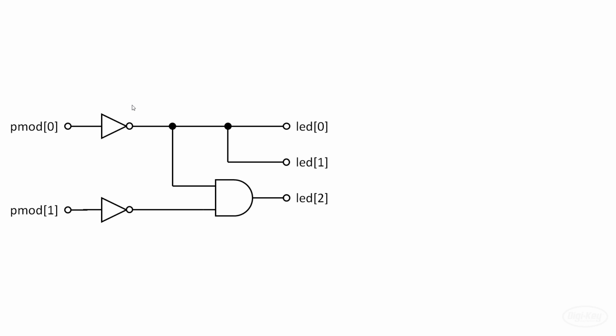A vector in Verilog is just a way of grouping inputs, outputs, and other named containers together. It's similar to how you might use arrays in other programming languages like C or Python. Rather than assign a name to each input and output, we're going to group them together. A single named net, like what we were using in the previous example, is known as a scalar.